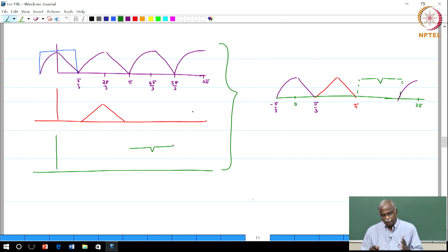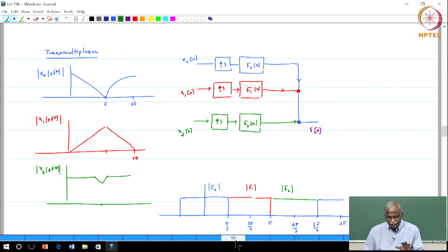The other element of what this structure is doing is that it took 3 signals, x0, x1, x2. You can think of these as 3 signals in the time domain, as time division multiplex signals. So you could have a green sample, a red sample, and then a blue sample, then again green, red and blue repeating. You can think of them as interleaved; you de-interleave them and pass them through each of those branches.